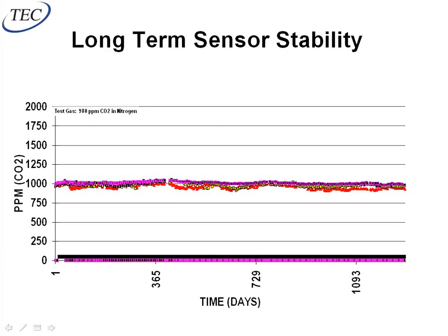Now, usually at this point, someone asks me, well, am I going to overcool by opening up those zone dampers on the VAV boxes for CO2? The answer is yes, and the answer is no. The first thing you have to remember is I'm not going to be modulating this damper open more than a normal job. I'm actually going to be modulating it down from a normal job. So if my normal job was 300 CFM minimum, maybe on this job with CO2 sensors, I put 100 CFM minimum on that VAV box, and I modulate it between 100 and 300.